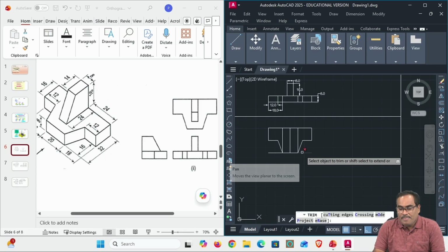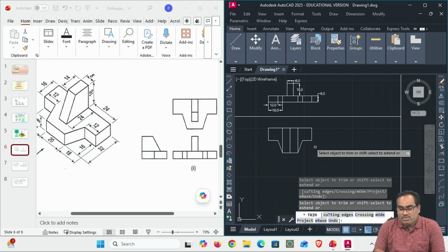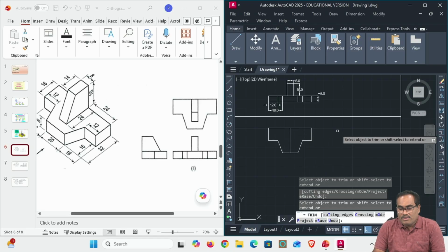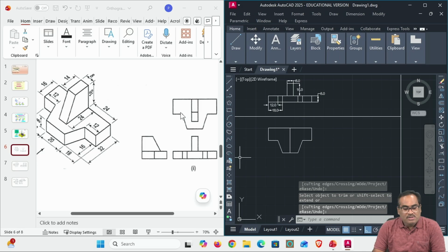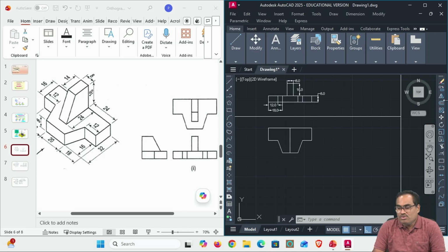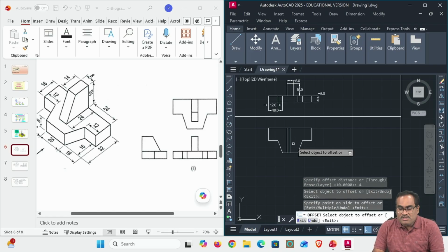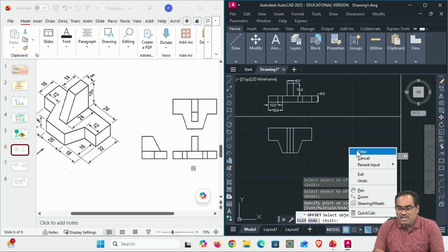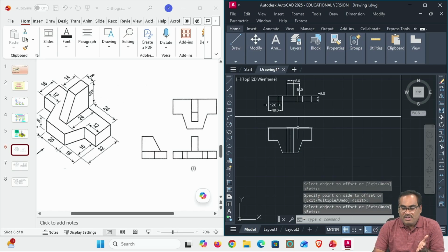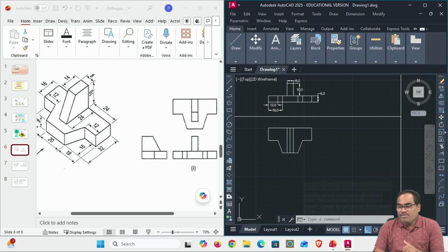If you want to go to trim, you can trim, right? So later you can remove this one also. Okay, middle, keep the middle line. So right, what happens here, you know, there is a wedge, right? That wedge, what happens? The wedge is 8 mm thick, and then a total 24, and then there is a step at 14 also. Okay, first go to offset 4, either side 4, 4. This side 4 and this, both sides 4, 4, and then offset this one 14 and 24.